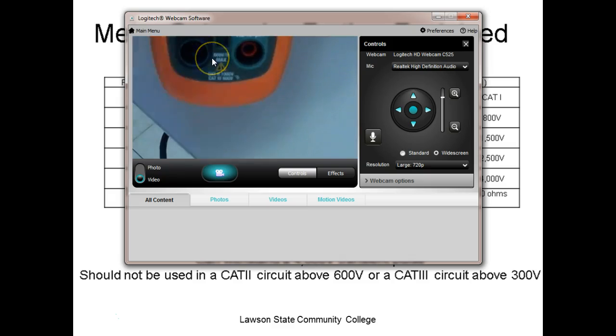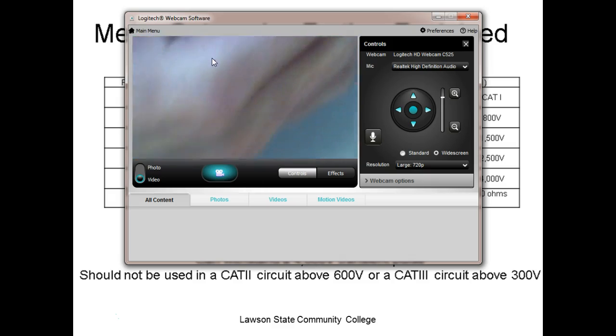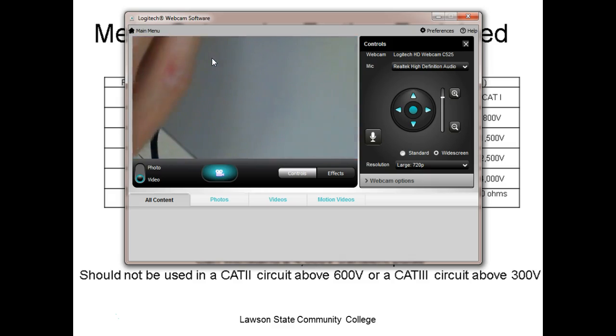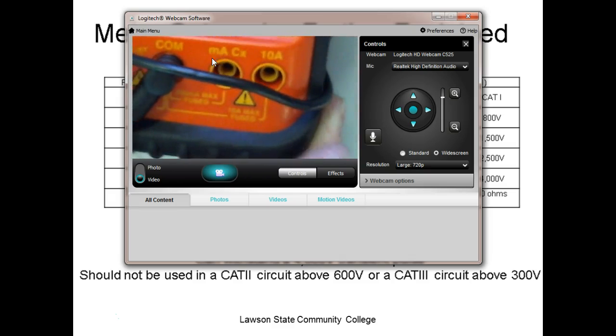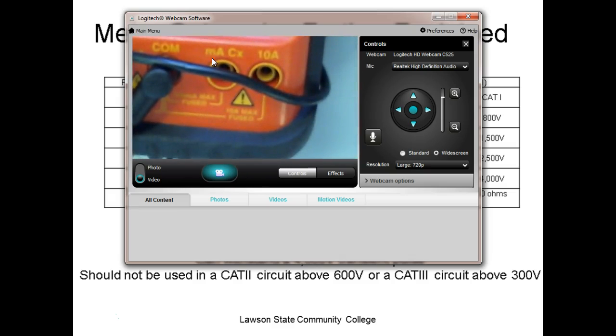So normally it's going to be down where we connect our meters. Now you see this? This has no rating. So what does that mean? Well, it don't mean much. It says this meter came out before the rating standard. It don't mean it's not a safe meter, but we don't know. Y'all understand? We don't know what type of surge it would protect me against.